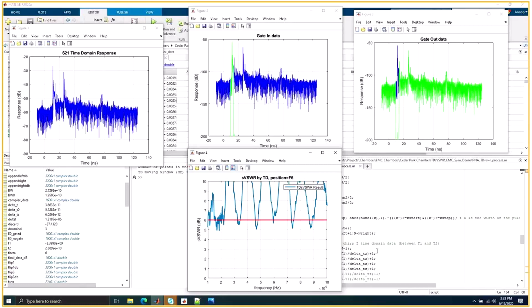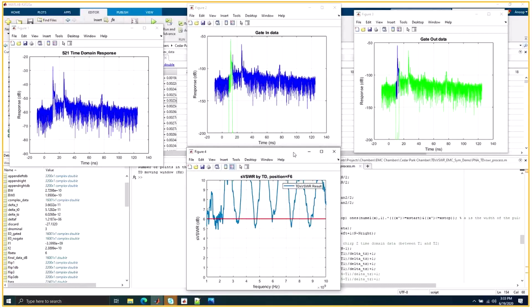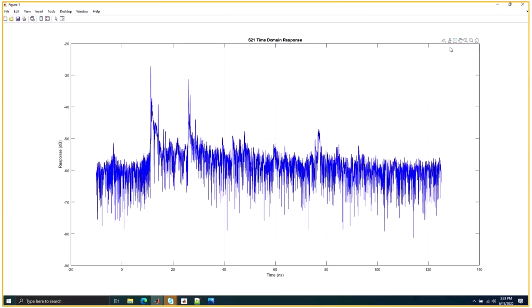But in a real world scenario, as Zhong showed in the presentation, where we took out an absorber to represent a bad absorber on the wall or a deteriorated absorber performance at some location, one way to find that would be to go back to this time domain view, expand this, and then apply another notch filter at these individual reflection spikes, right?